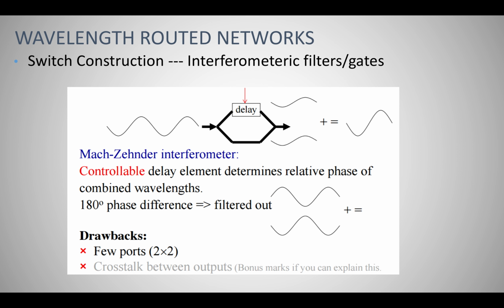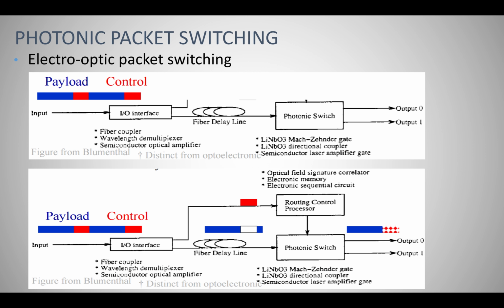So the fourth part is the photonic packet switching. From the picture, we can see that the payload travels over a light path from source to destination. No optoelectronic conversion occurs within network switching elements. Control information may incur optoelectronic conversion, and may even flow on an auxiliary electronic control network.